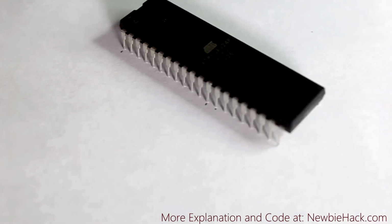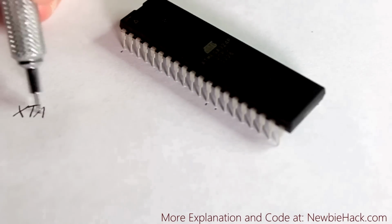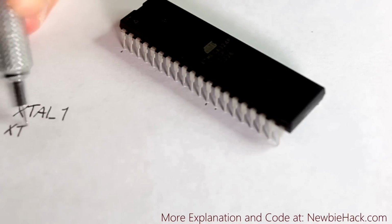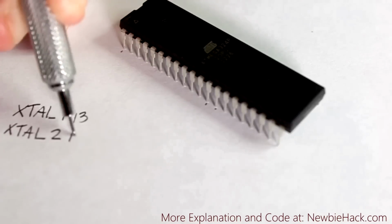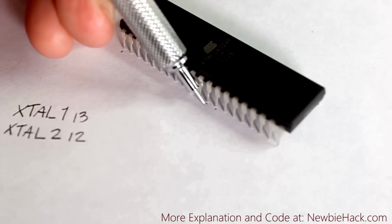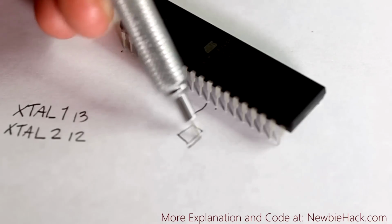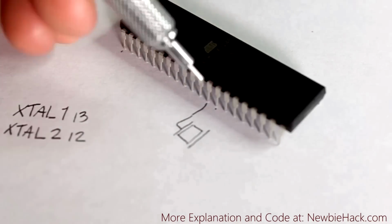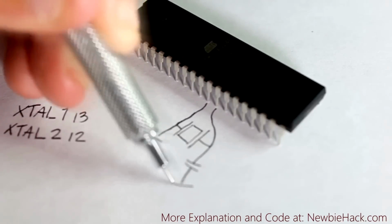so what we're doing here with 22 picofarad is fine. On the ATmega 324, the crystal is connected to the XTAL pins, XTAL1 and XTAL2. The XTAL1 is on pin 13 and the XTAL2 is on pin 12 for the ATmega 324P. And the schematic symbol is a rectangle or a square with a couple lines next to it. And then the capacitors are connected back to ground.